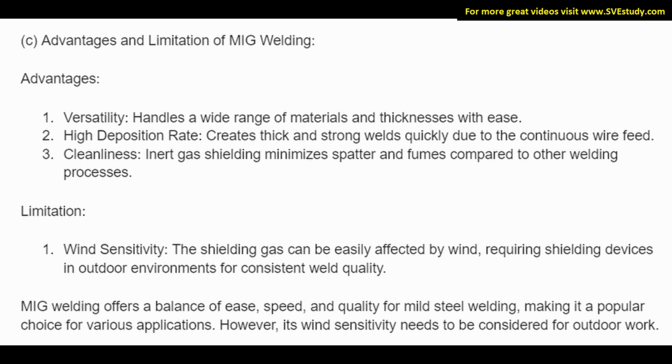Limitation. 1. Wind sensitivity. The shielding gas can be easily affected by wind, requiring shielding devices in outdoor environments for consistent weld quality. MIG welding offers a balance of ease, speed, and quality for mild steel welding, making it a popular choice for various applications. However, its wind sensitivity needs to be considered for outdoor work.